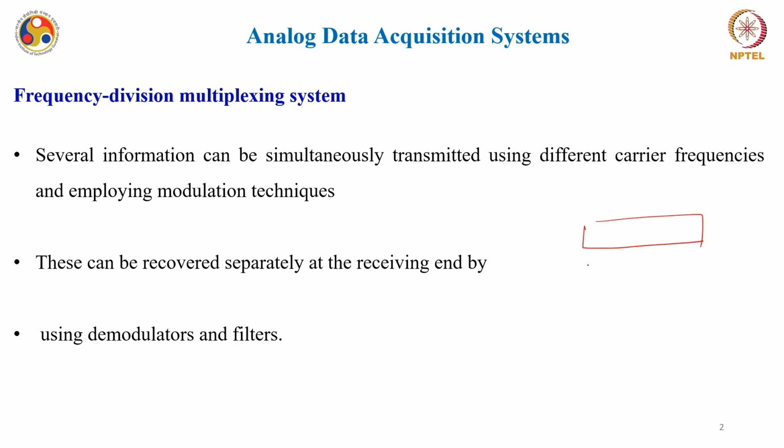Say, for example, we were using a single channel divided in time. At the 0th second we were transmitting temperature, and at the 10th second we were again transmitting temperature, but in between, say at the 7th second, we were able to transfer a pressure signal or humidity signal.